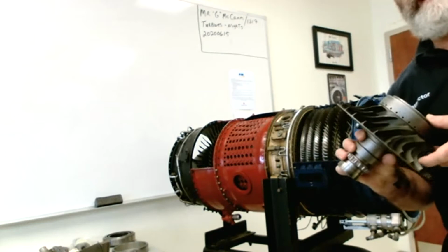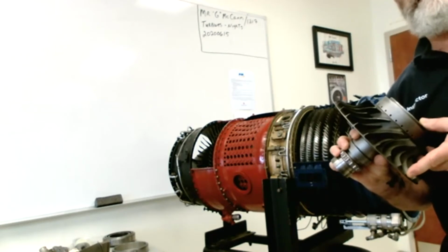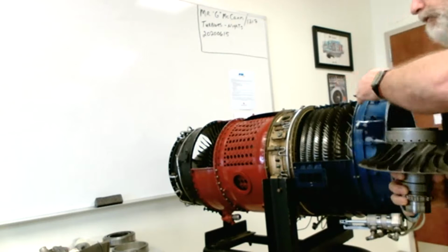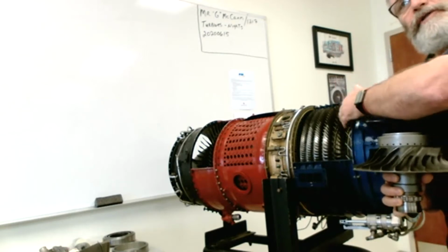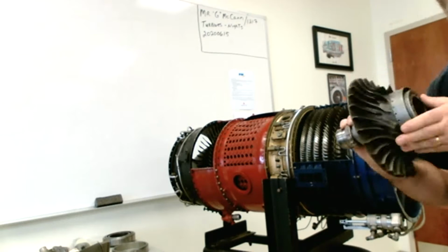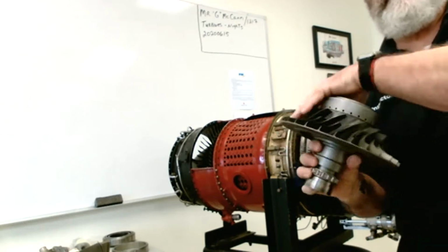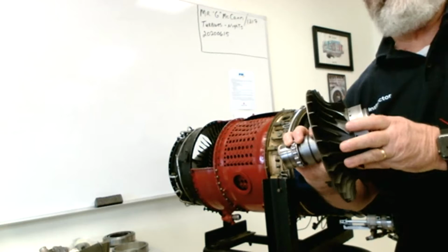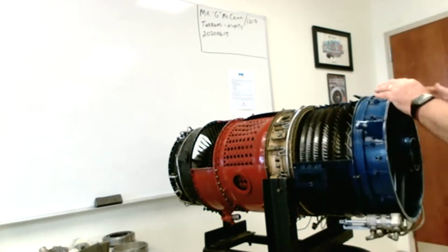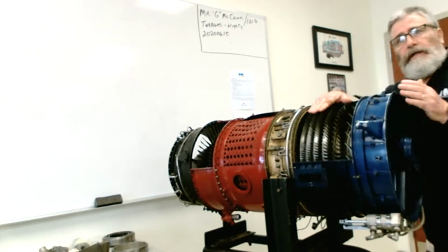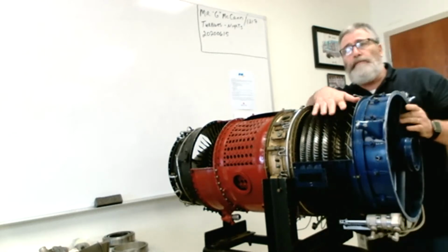We're not going to get into heavy detail on this. This is just a general discussion, all right? So, one stage of compression is a rotor and a stator in an axial. The stators are divergent. One stage of compression on an impeller or centrifugal is an impeller and a diffuser, all right? So, staying on the axial, these are by far the most popular